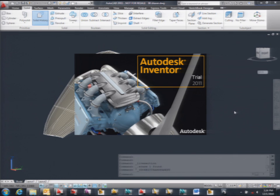So maybe what you may want to do is, let's say that you have 2 surfaces and you want to subtract kind of a cylinder from those, right? I may just draw a circle, trim both surfaces, and create a blend with G0 on both sides. So I get the same result, but I get associativity. It all depends on what you want to do at the end of the day.